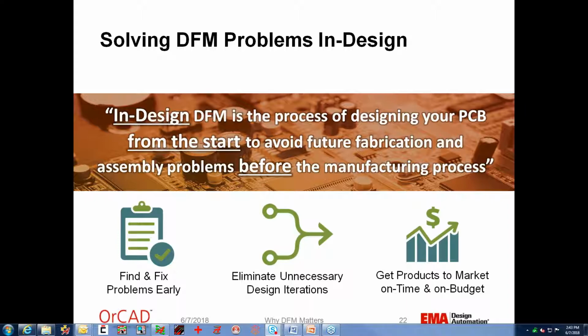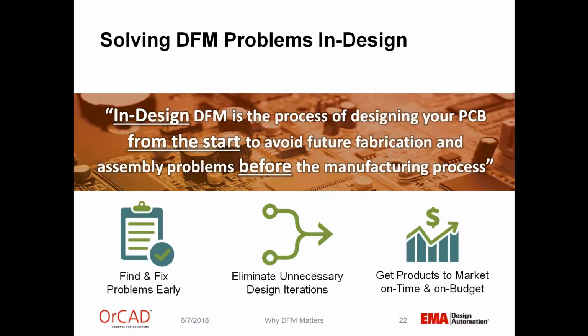All right, I think we'll do one more question here. When you run through the DFM DRC checks, you change pad stacks within the PCB database. Does your DFM tool summarize the changes in a form where you can use it to update your library or send it to a librarian for updating the library? So good question. What I was doing was just editing the ones in the design themselves, but there's a couple ways you could deal with that.